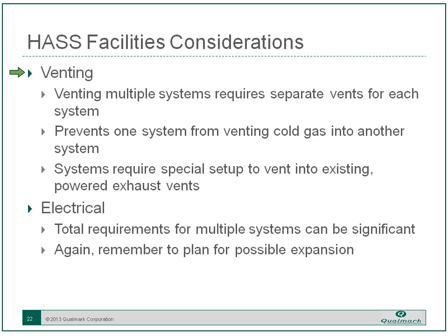So it can mess things up for you if you try to run everything into the same vent. Also, you're often tempted to say, look, I've got this big in-house vent system because I have hoods over all my reflow lines and everything, so I'm just going to pump it into those. Well, once again, you're under pressure and you've got a cryogenic cold gas, and you'll have a mess on your hands if you try to do that.